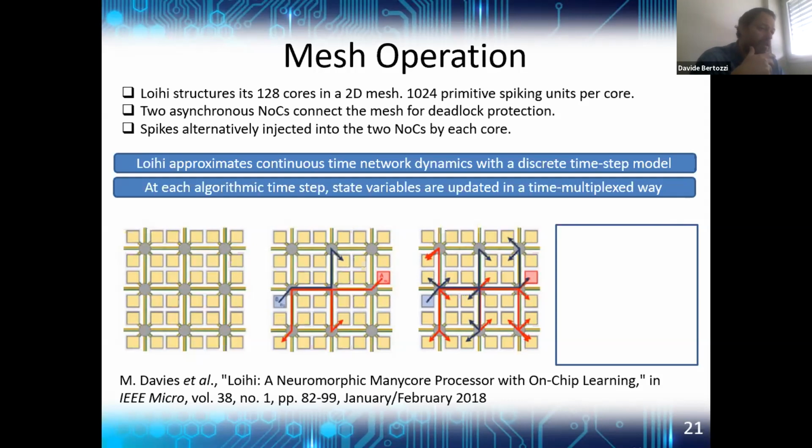There are some solutions that come with multicast directly in hardware, but in this case, it is implemented in software. In fact, to multicast spikes, the output process of each core iterates over a list of destination cores for a firing neuron's fan-out distribution and sends one spike per core. So it is changed into an iterative transmission process.